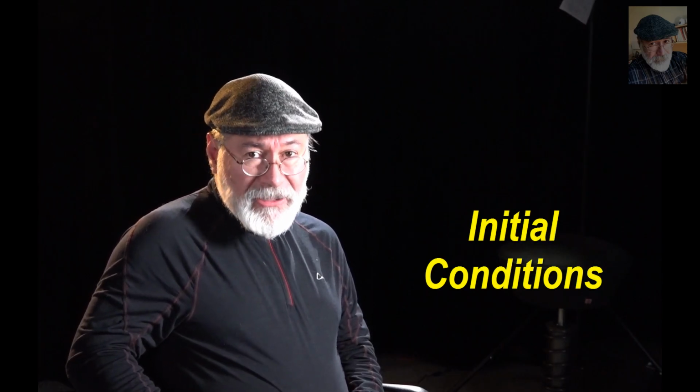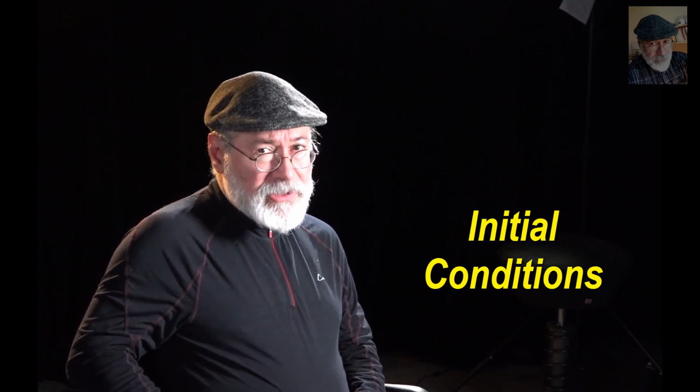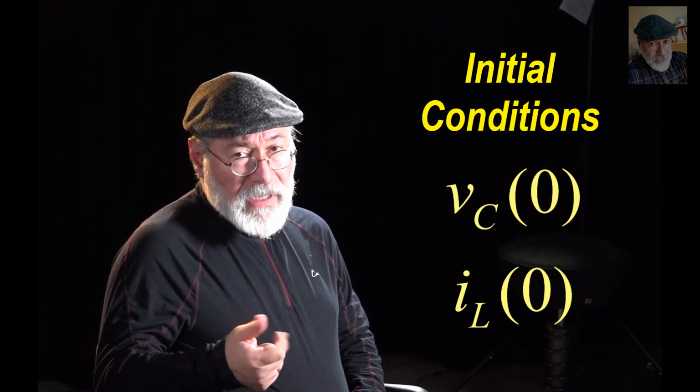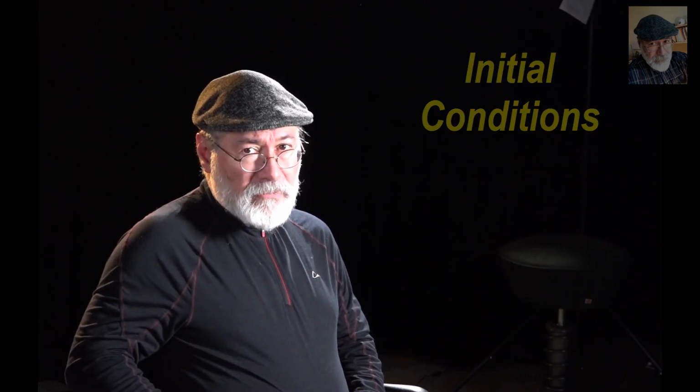But you and I remember from our math courses that to solve the differential equation, we need initial conditions. Well, in an electronic circuit, the initial conditions are the voltage in every capacitor at t equals 0, and the current in every inductor at t equals 0. We will have another whole video just for that, initial conditions in electronic circuits. And then the video right after that explores how to solve those differential equations in detail.